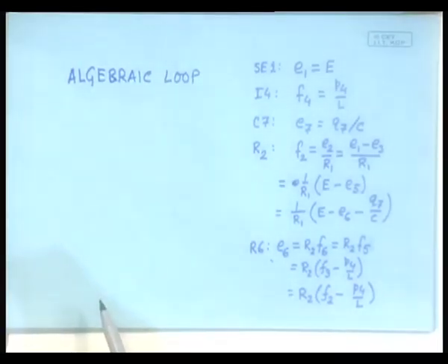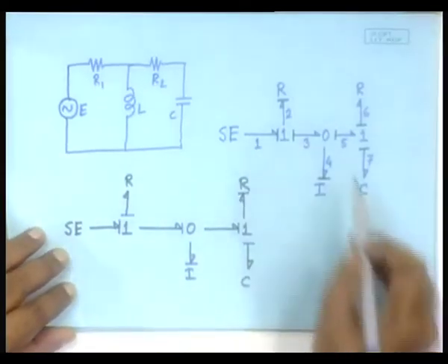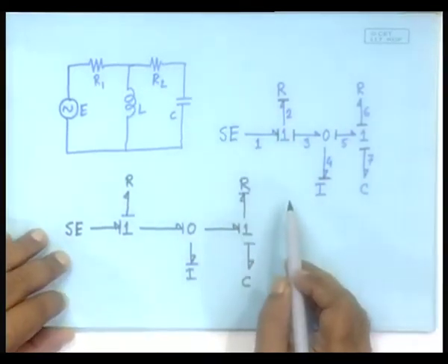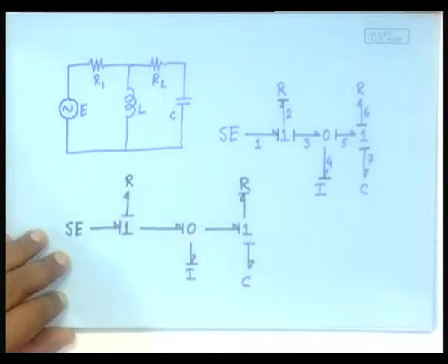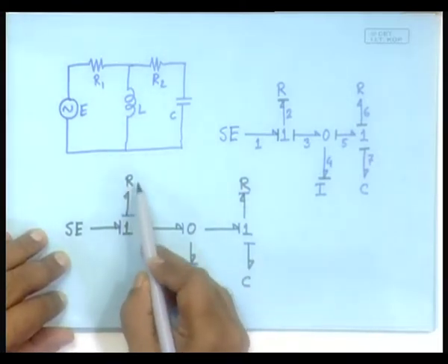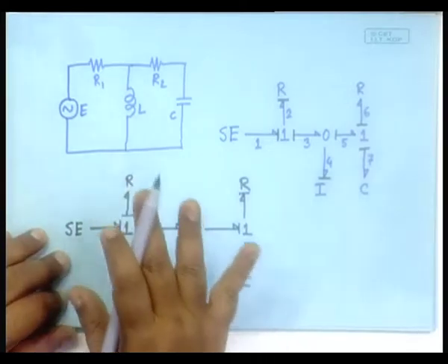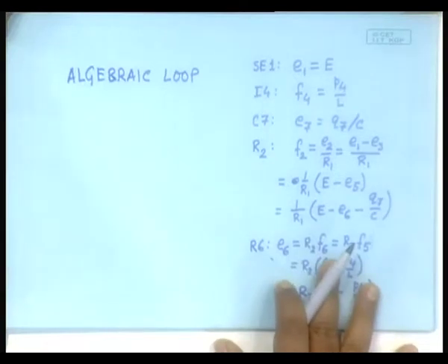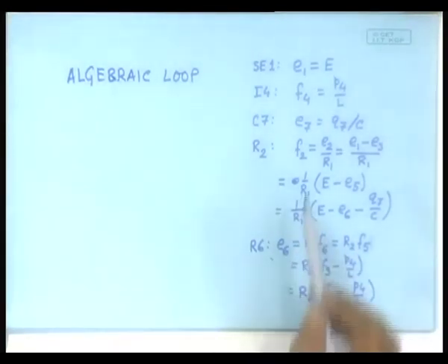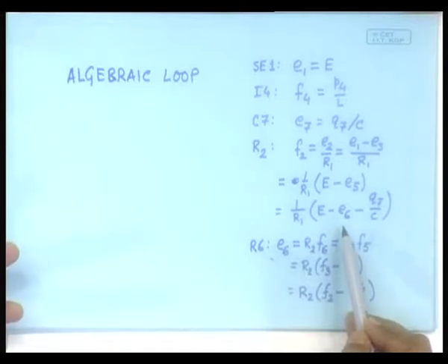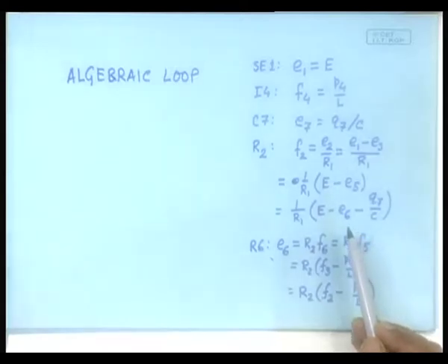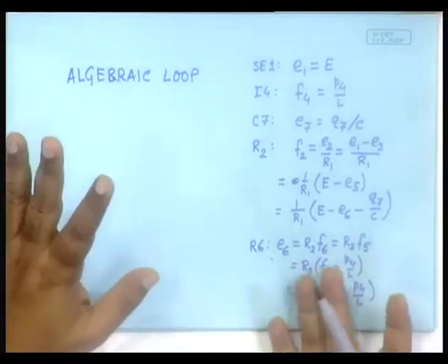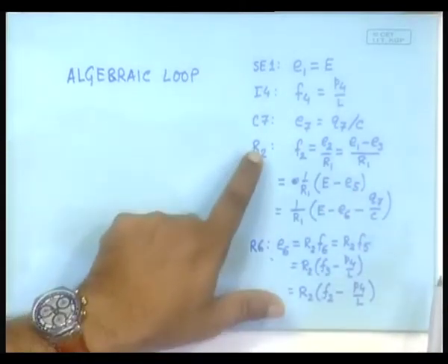And whenever there is an indeterminacy of the causal structure, so that you are having to, out of your hat, put a causality in one of the R elements, it immediately indicates that you will have this kind of problem while obtaining the differential equation. But you would notice that that is not a big deal. Why? Because you have two equations and two unknowns, right. The moment you have two equations, two unknowns, you can always solve it and obtain these two individually. So, they are actually determinable, no problem, but you have this causal loop.